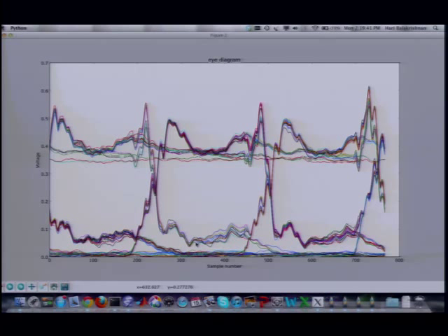Okay, so when you scale, we're not really seeing too much. Well, we are seeing scaling. What kind of scaling are you seeing here? We have 0 to 1 transitions, but we also have 1 to 0 kinds of transitions. What would you want to see for a linear channel for how the 1 to 0 transition behaves relative to the 0 to 1 transition? What would you expect on a linear channel? From superposition, you would really expect to see the same shape on the downslope that you see on the upslope. So when you look at the upward transition here, you see a certain shape. Well, it's not quite matched on the downward slope here.